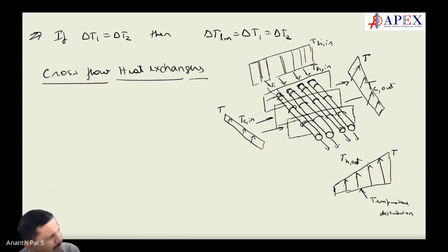That also is possible. It's similar if you don't take into effect natural convection. If you take natural convection, then what should happen? If it is cooling by natural convection, not by forced convection, then what should happen? Hot fluid should go like this, and cold should go from bottom to top. So don't have to worry. Natural convection makes it happen.